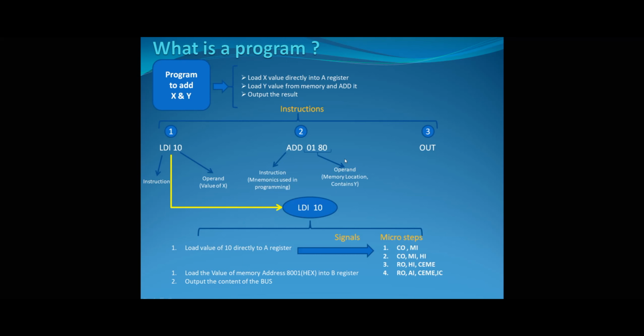Now, another important point that I would like to mention here is in regard to the memory structure in Bravo. In Bravo, we will be using little endian format when addressing our memory. That means that when we have an instruction like ADD, and we are pointing to a specific memory address in front of it, we need to put the low byte first and then follow it by the high byte.